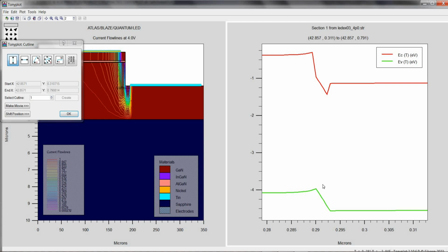That is the primary reason that we cannot have thick layers of indium gallium nitride, because if we grow them thicker, then these points would be farther away from each other, and we will have less probability of electrons recombining with holes in the active layer. So in indium gallium nitride LEDs, in which the active layers are indium gallium nitride, the thickness range is like 2 nanometers to 5 nanometers. In our case, it's 3 nanometers.